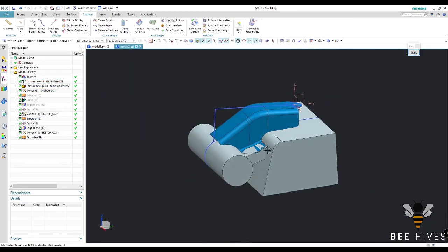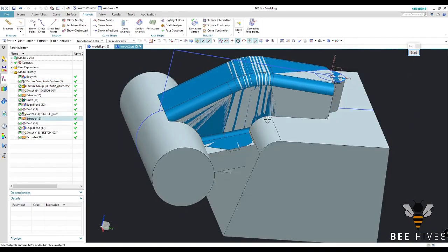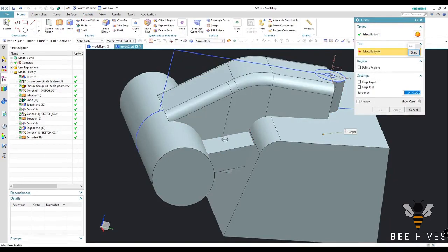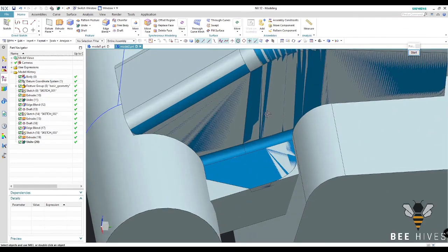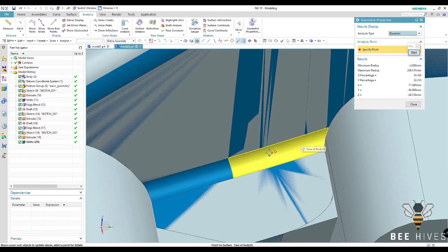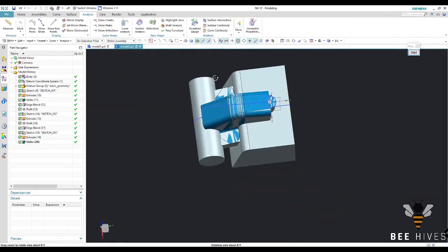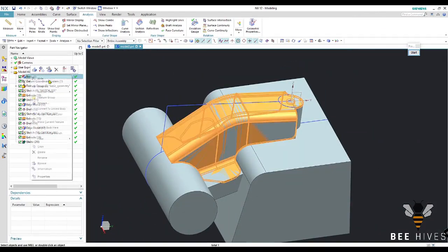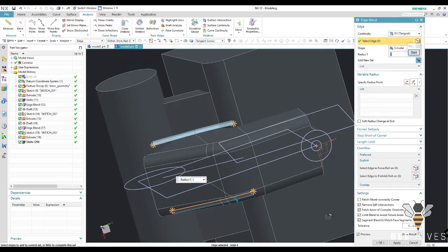Let's say okay. Now you have this, you have the basic geometry again. Now simply what you can do is unite it. The first, second, say okay, check for the blends value. Again, analysis, geometric properties, it's 2 mm, both the sides should be the same. Okay, that's it. So I'm gonna hide it again. I'll apply the blend. It seems to be 2 mm here.